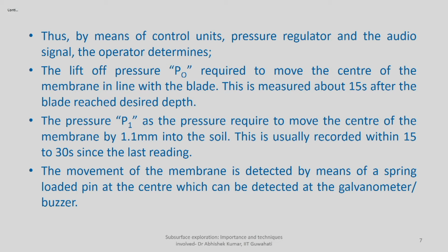Thus, by means of the control unit, pressure regulators, and the audio signal, the operator determines the readings. You have a control unit which will control how much pressure you are applying, a pressure regulator which will measure the pressure applied, and the third one is the buzzer. Based on the audio signal, once the buzzer sound is on, that will indicate that the necessary movement in the membrane has happened, and now you can measure the pressures.